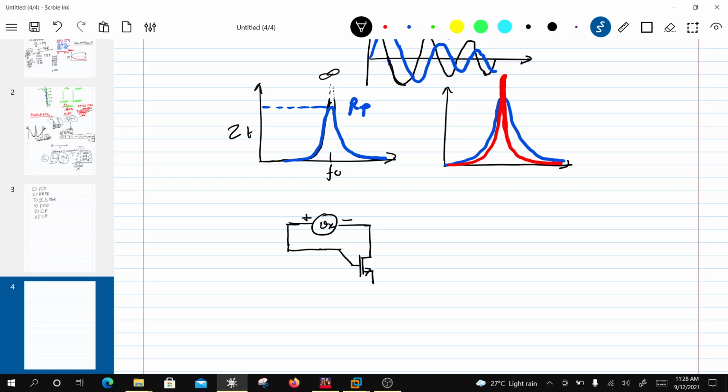and similarly I can go this way and cross couple a transistor like that, right? So if I do this, this can be a source of negative resistance. And how? Let me show you how. Now if I remove all the parasitics of the device, and this is a voltage controlled current source, then you are going to have